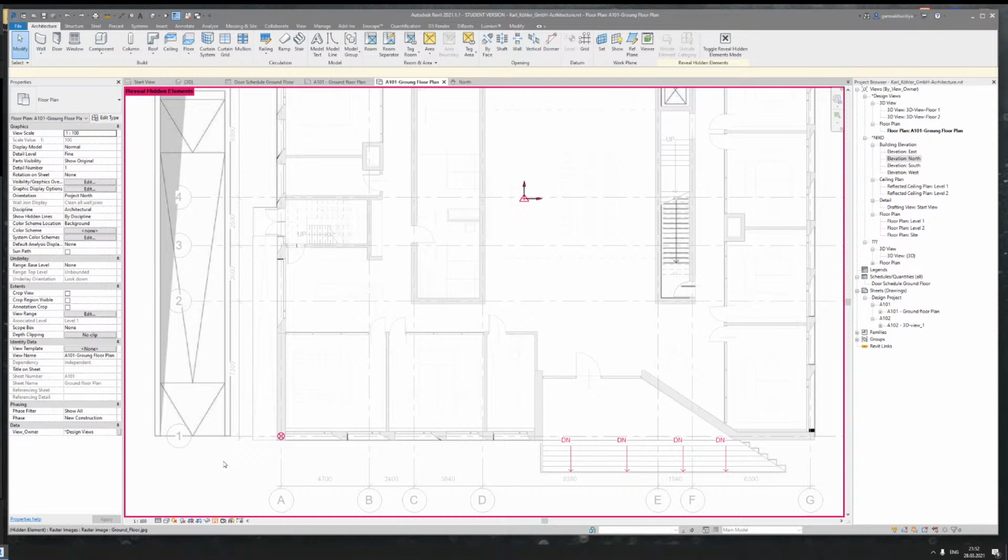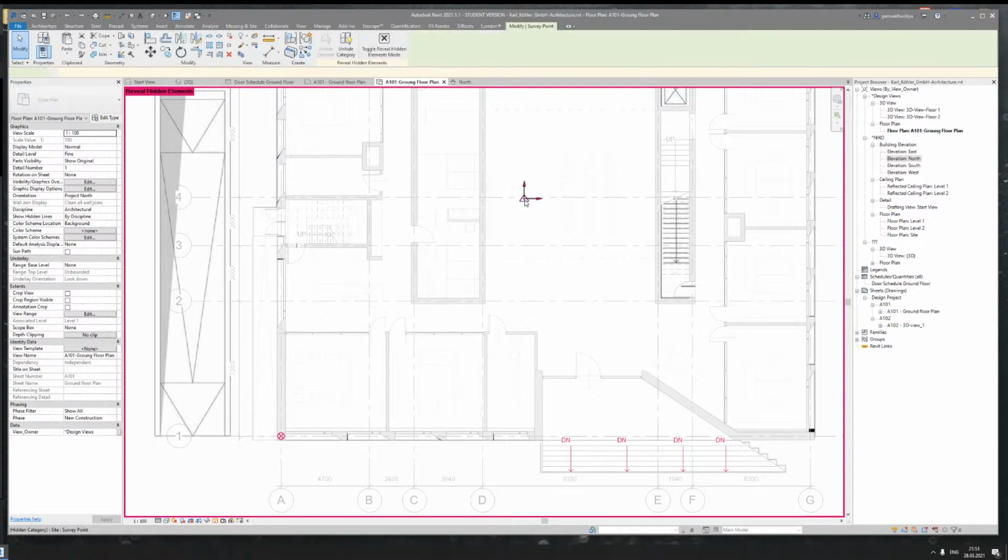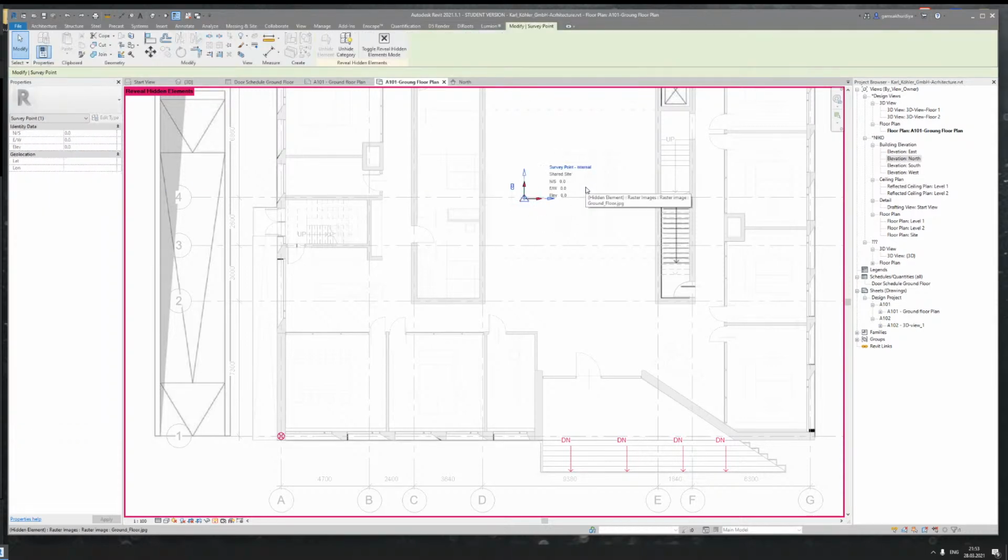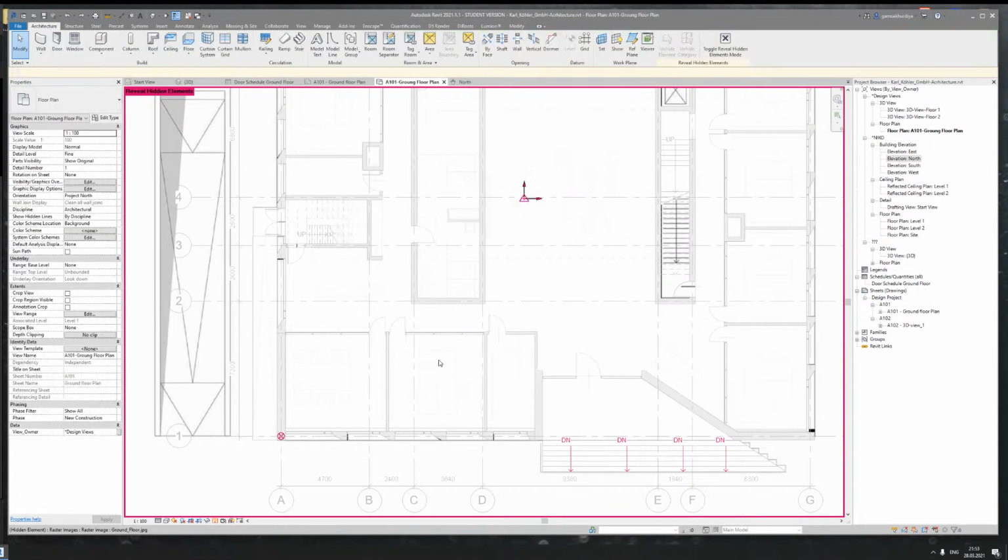they have a really specific coordinate point. It's really strange. So for that part, we are using the global coordinates, and it's working really perfectly. But it's a real headache when you get the model from different programs. When you're working in Revit, shared coordinates is a really nice thing.